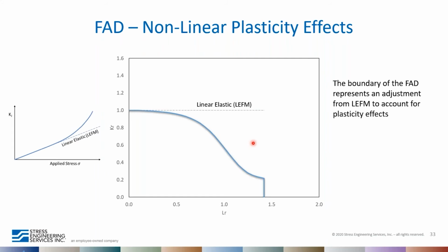And so you'll remember how we talked about the deviation from linear elastic fracture mechanics previously, and the shift, the difference, the change from linear to nonlinear fracture mechanics really is captured in the FAD by this adjustment here to account for plasticity effects.